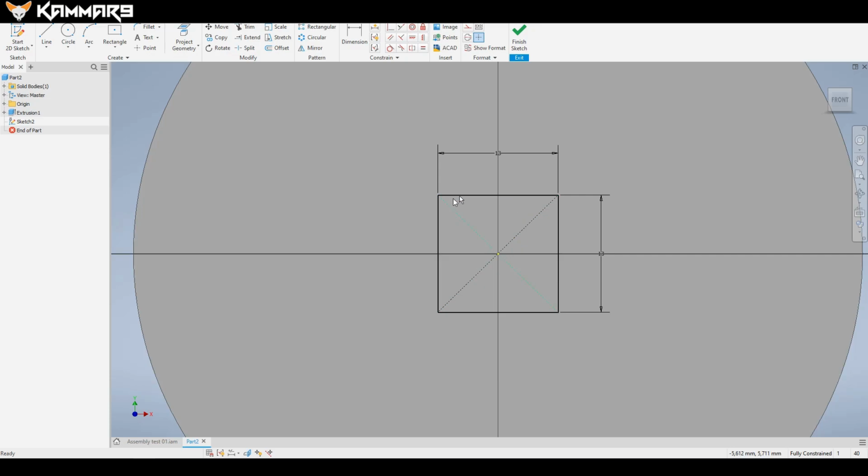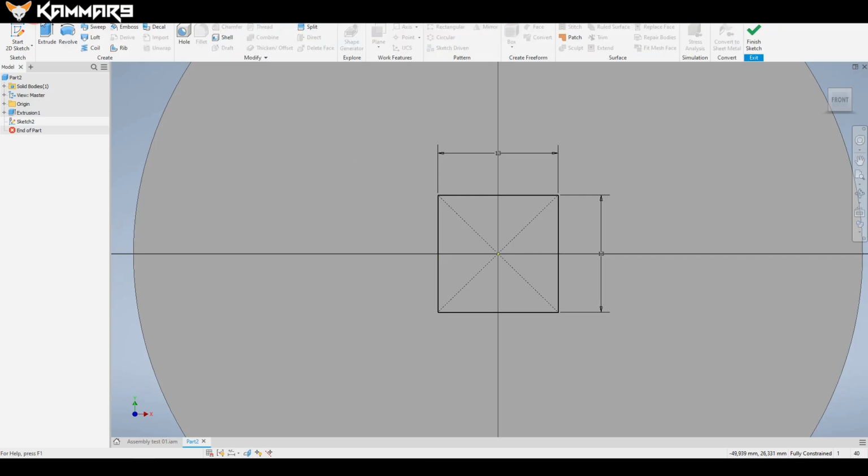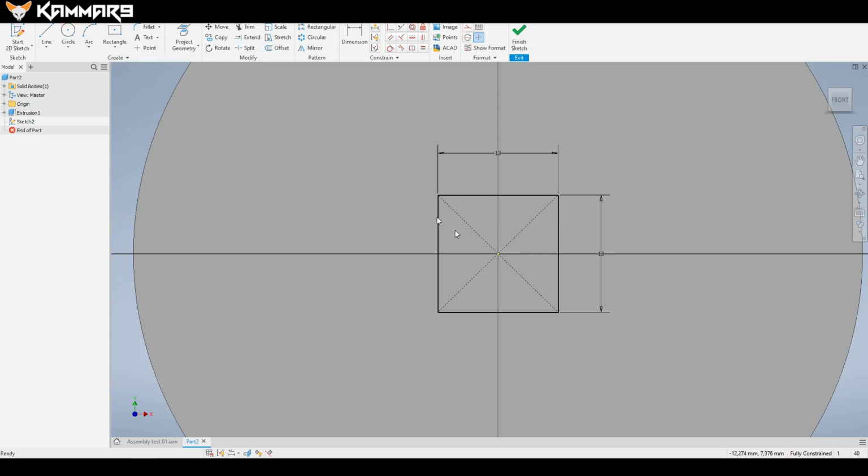And I want to add here a chamfer that I can do in Fusion, but you can use this one, okay, and add chamfer in the feature in 3D model, as you can see here, fillet or chamfer here, okay. So return to the sketch.